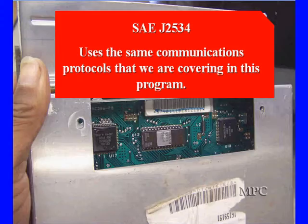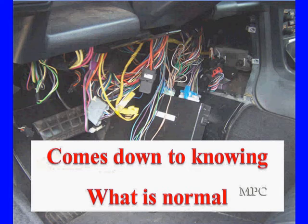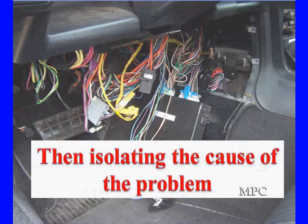So that's really important to you, because you've got to ensure that communications are normal before attempting to flash program modules. If you're getting garbled communications, you're not going to get a good program. So keep that in mind, that you're going to need good information. It comes down to knowing what is normal. And we're going to show you that. Then we're going to show you how to isolate the cause of the problem.